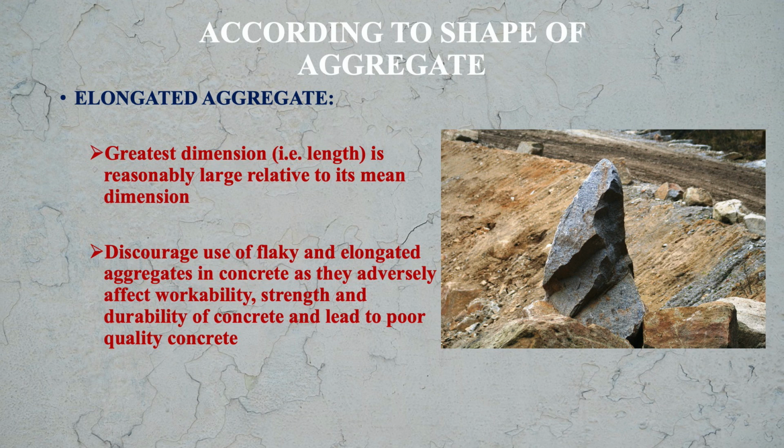So generally we discourage the use of flaky and elongated aggregates in concrete as they adversely affect workability, strength and durability of concrete and lead to poor quality concrete. So that way their use is restricted. Now next is the unit weight of aggregate.